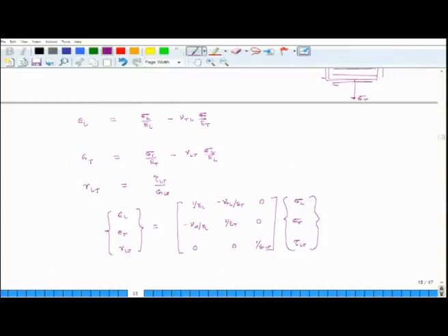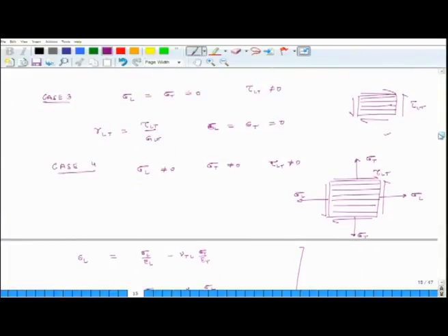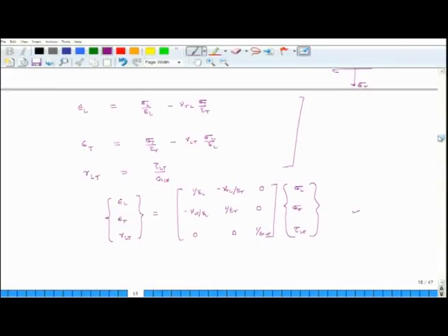Okay. So, what we have shown so far is now with these relations. So, this is the matrix form or this is the general relation, a conventional form. If we have a specially orthotropic lamina which is subjected to stresses in longitudinal, transverse and shear directions, then we can predict its strains using these equations.